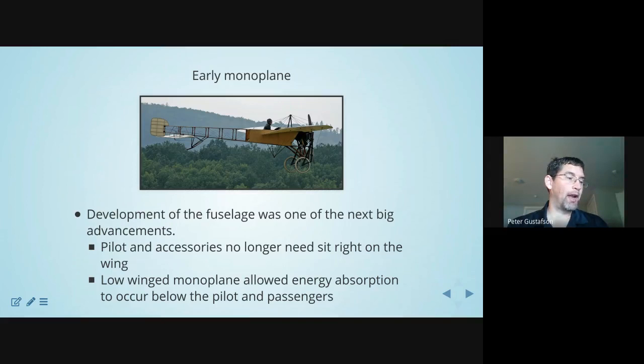Joel says supporting the bending moments from the CG being away from the wing mounting point. That's an interesting point, and we'll address what that means. You've referenced some keywords: bending moments. These are forces times distances from a reference. Absolutely, that becomes part of the challenge. So we'll get back to that in a little bit.